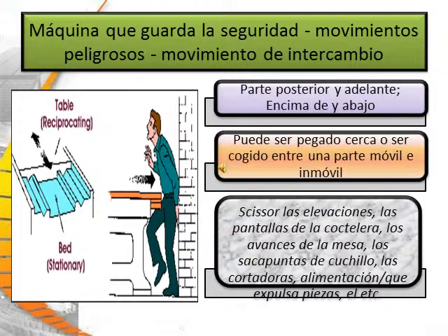A reciprocating motion will be back and forth, up and down. It may cause someone to be struck by or caught between moving and stationary parts. Examples of this would be scissor lifts, shaker screens, feeder tables, knife sharpeners, slicers, feeding and ejection parts, etc.